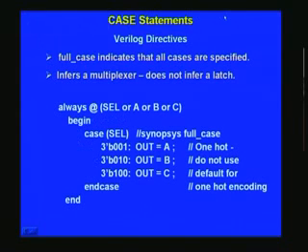And we have also considered case statements, and we will now see what Verilog directives are. There are basically 2 directives called full case and parallel case, and this indicates when you have a case statement here. Let us consider 3 bits of information. If all the conditions are specified here, obviously it is not specified here, and for 3 bits you have 8 possible states, and only 3 such states are considered here. And what happens to the rest? When such a condition is encountered, will it be encountered? That is the first question we will have to put to ourselves, and if it is encountered, we have to see remedial action for that, and for the time being we will see